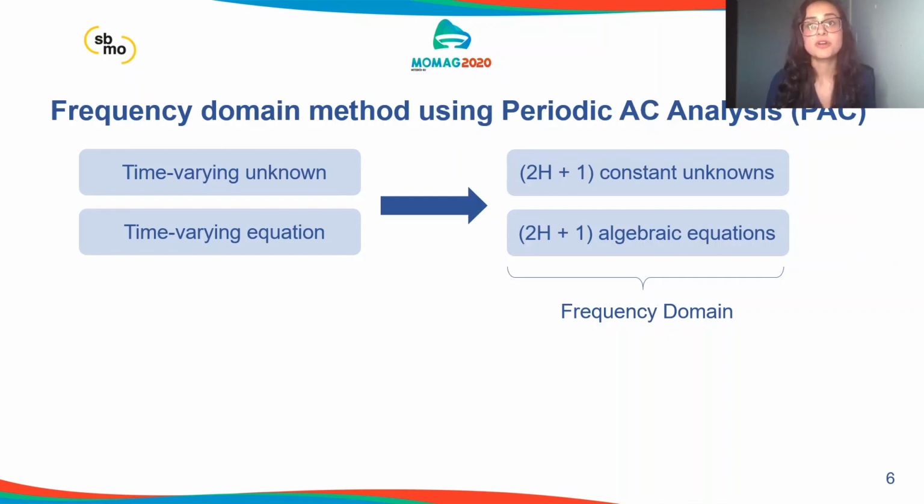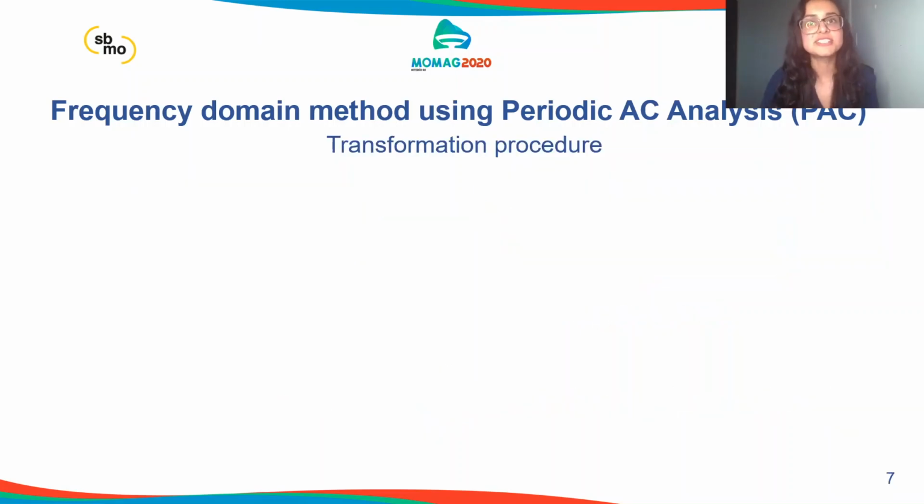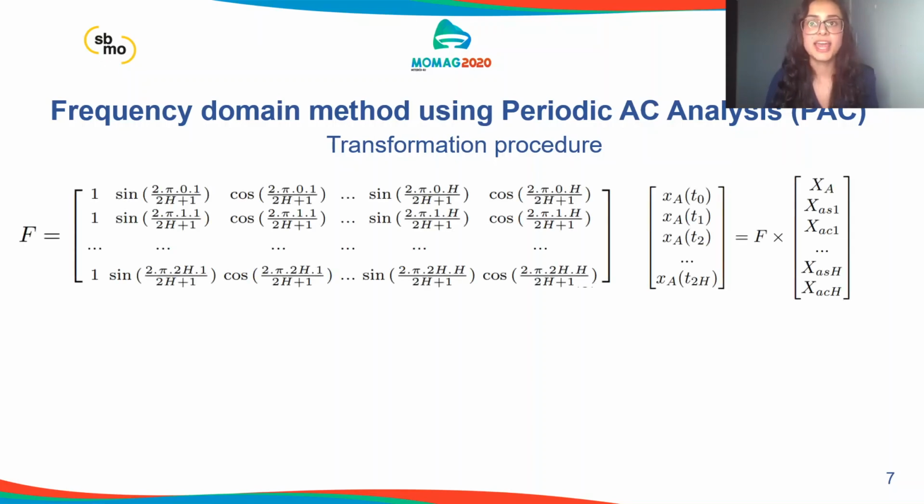simulation. By transforming all the characteristic equations of the circuit components, given in the time domain, to a set of equations independent of each other in the frequency domain, the steady-state response of a nonlinear circuit powered by a sinusoidal signal is represented by a vector of values corresponding to amplitudes of sine, cosine, and constant components, as presented in this equation. For nonlinear circuits, the frequency domain vector of amplitudes is converted to the time domain, aiming to handle the nonlinear function in the time domain.